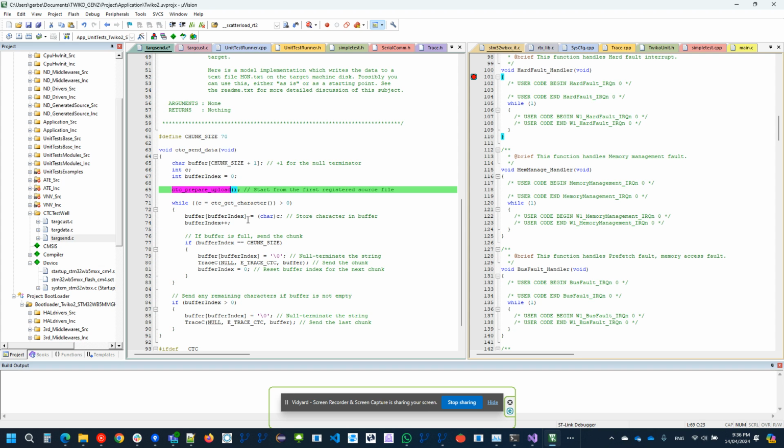What did you cover specifically? And you have various types of coverage, by the way, supported by CTC. I will show you specifically a type of coverage called statement coverage, also known as line coverage, and decision coverage as well. They're both supported at the same time. The more complex your coverage type is, the more memory it consumes, because more instrumentation is required.